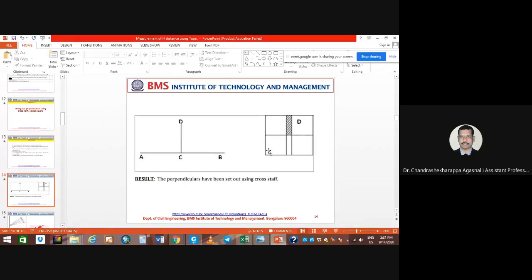So, for example, this is your ground, this is your survey area. You need to survey it A, B, C, D like this, and you need to make the entire area into a block leveling or a grid. You need to direct the 90-degree angle towards here.